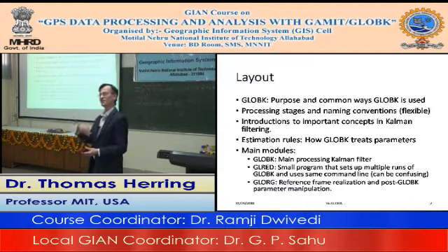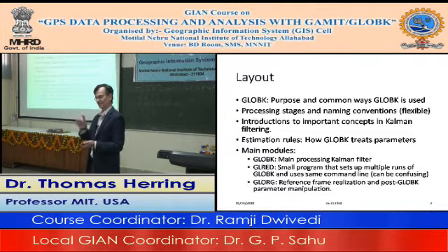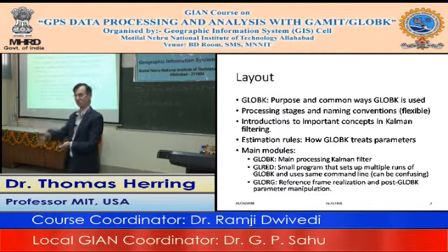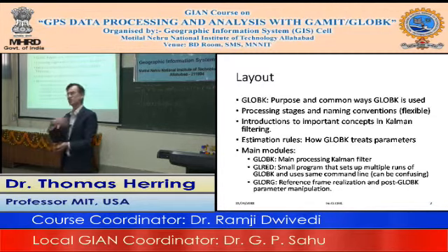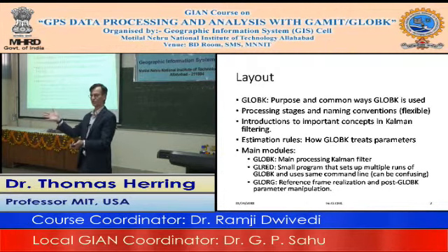Well, Kalman filtering is a minimization estimation, the same as least squares is, except it has the concept that the things you are trying to estimate are actually changing while you are collecting data to try to estimate them. And that changing of the parameters as a function of time is called the process noise.